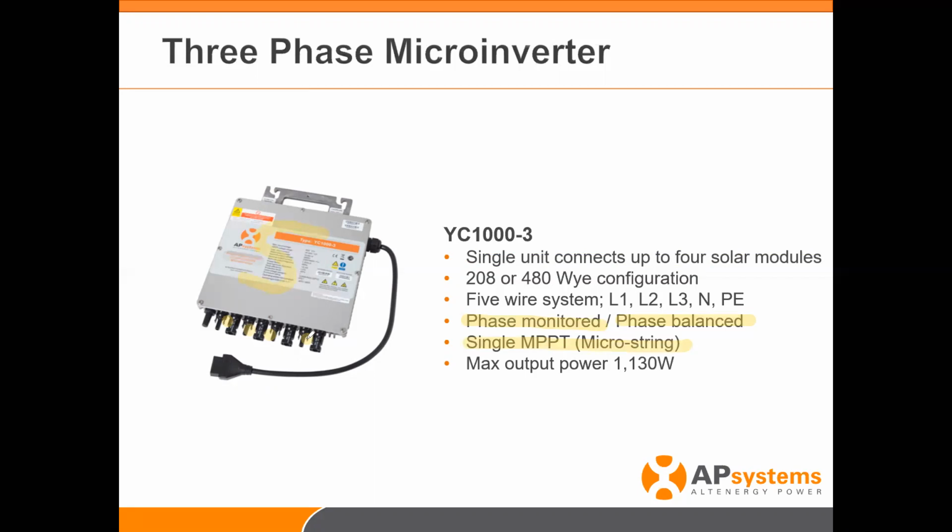I know in a lot of commercial applications, module sizes are getting bigger. So depending on your level of clipping acceptance, we clip at 1,130 watts. So looking at the modules' STC versus PTC, we can right size the modules and utilize the right number of channels to maximize the power coming off those panels on that roof through this inverter.